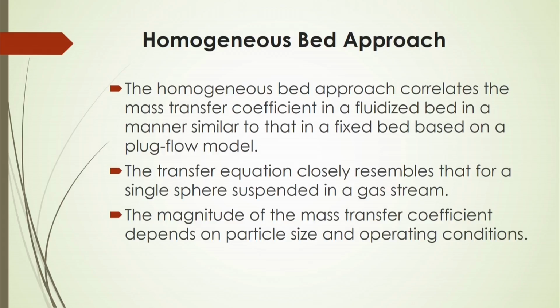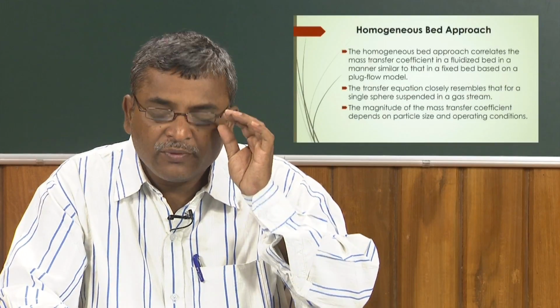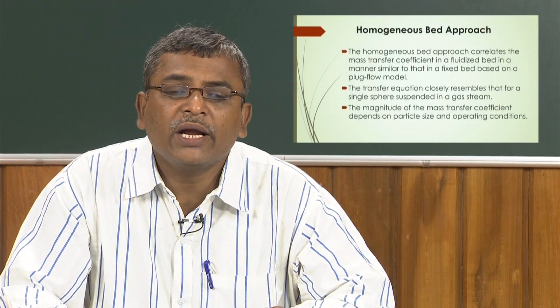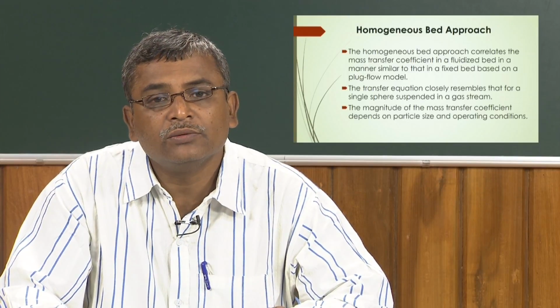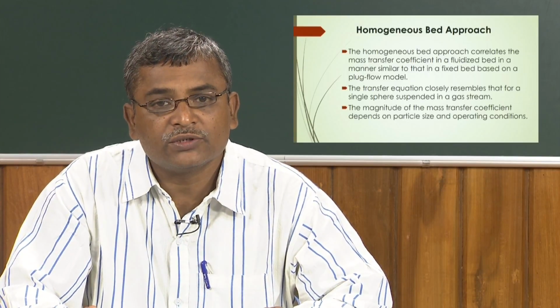In a fluidized bed you will see geometrical variables like reactor size, diameter and cross sectional area, length of the column and these things. And then the operating variables, or dynamic variables, such as gas velocity or fluid velocity in a gas-solid fluidized bed, and in a gas-liquid-solid bed, the gas velocity and liquid velocity.